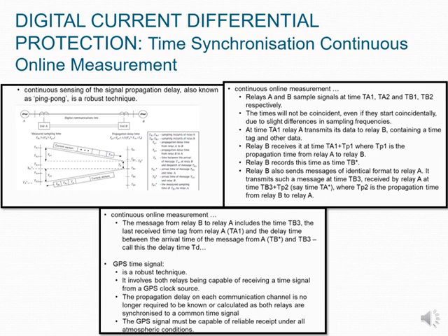So there are various times. I'm not even going to go into that, but I want you to understand that when these comparisons are being done by the two relays on either side of that line, we need to account for the time differences so that we know exactly when your fault actually occurred, as an engineer that needs to do an investigation later on.